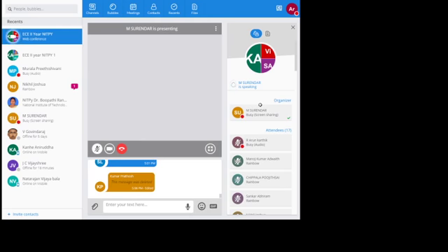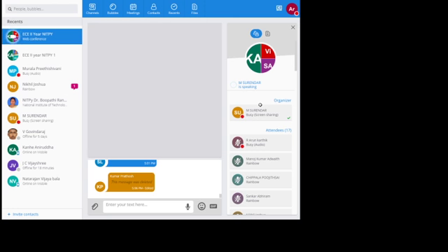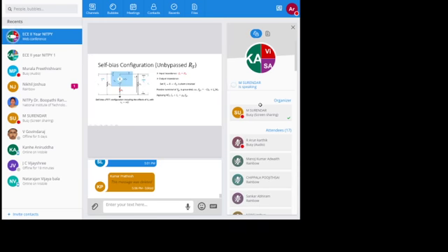By applying KCL we obtain two equations for VGS. The current flowing through the resistor RS is ID plus I naught. VGS is of opposite polarity: the negative terminal of VGS is here and the positive terminal is connected to ground after grounding the gate. That's why VGS is equal to minus (ID plus I naught) into RS.